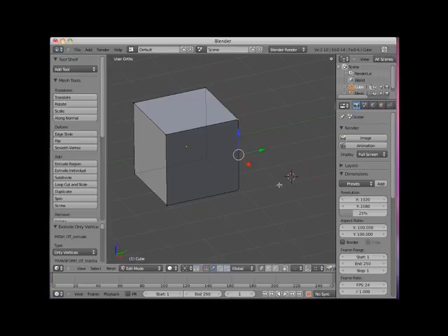Note that even though the vertices are selected, it appears now that they no longer have influence over the edge. Now, I'm not sure if this is a Blender bug, but to get back to normal vertex influence, we need to press Ctrl-Z and undo the operation to return to a vertex-selected influence. I'll press Ctrl-Tab and select Edge Select Mode.